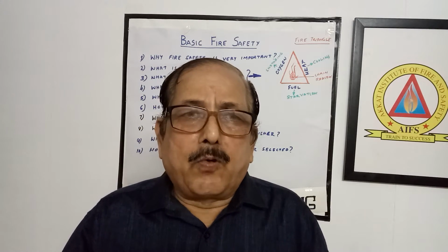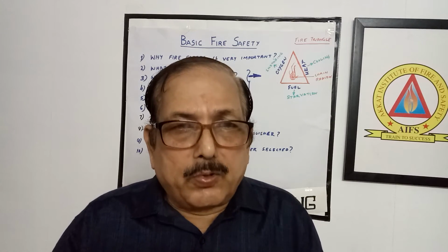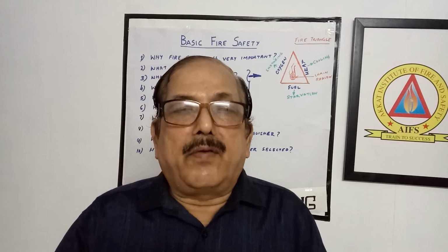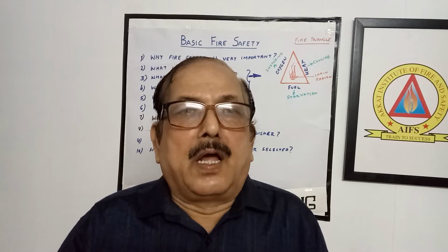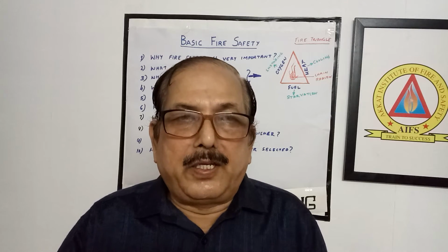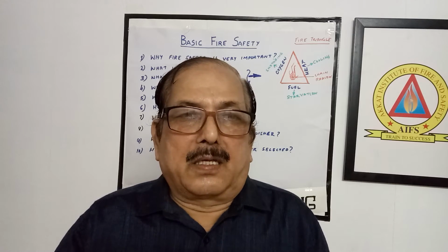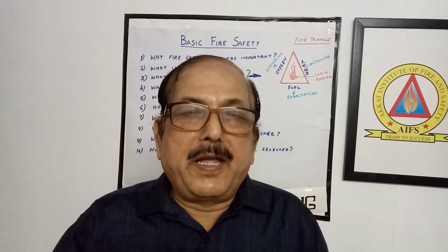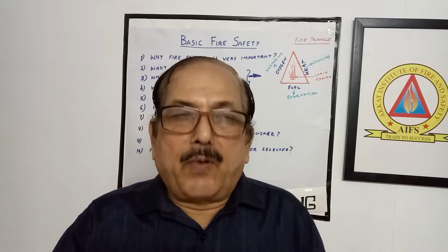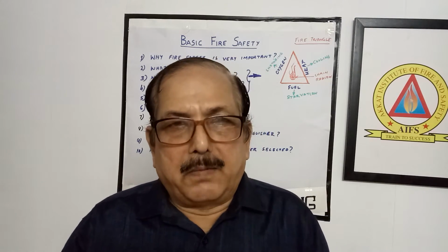Why? Because CO2, carbon dioxide, is a gas. As you also know, we cannot store any gas in the form of a gas; normally we store it by liquefying it. So about 75 to 85% of the cylinder capacity is liquid CO2. The remaining portion is only in the form of gas, at high pressure. When you operate it, automatically that liquid becomes a gas, like our LPG.